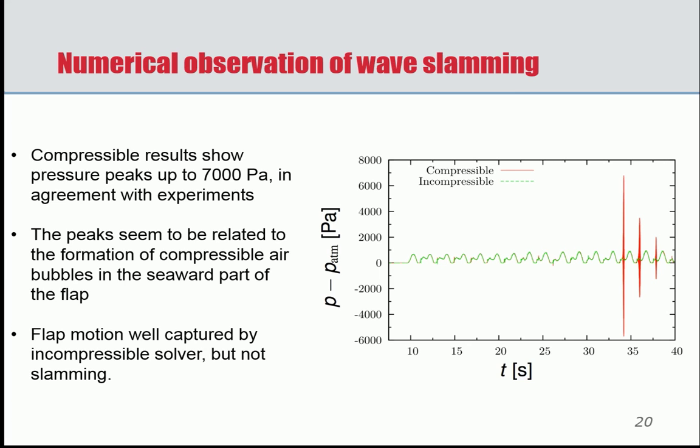Perhaps if you saw earlier on my slides, we saw maximum impact pressures in the order of 8 kilopascal, and that is very well represented here. Okay, so the key there is the flap motion, so the global device motion is well captured by the incompressible solver, but the impact loading is not. Okay, and that brings me to the end, and I'll take any questions if I have any time left.